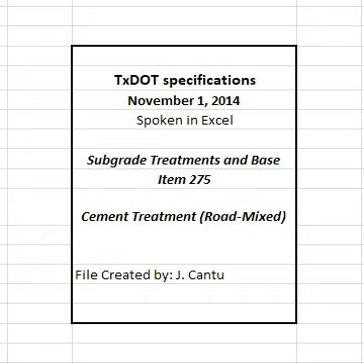Where subgrade is constructed under this contract, correction of soft spots in the subgrade or existing base will be at the contractor's expense. Where subgrade is not constructed under this contract, correction of soft spots in the subgrade or existing base will be in accordance with pertinent Items or Article 4.4, Changes in the Work. Where subgrade to be treated under this contract has sulfates greater than 7,000 ppm, work will be paid for in accordance with Article 4.4, Changes in the Work.